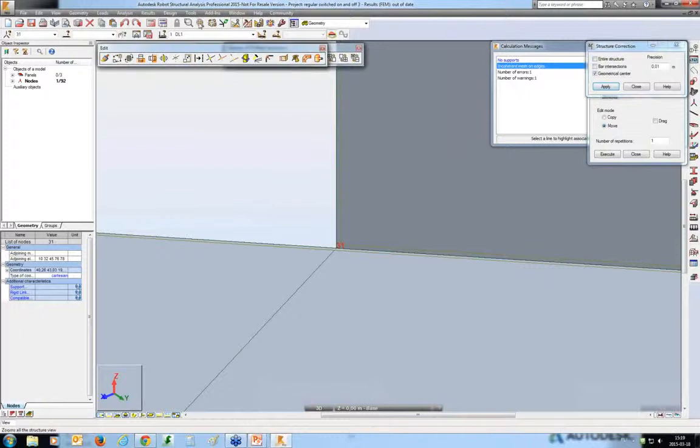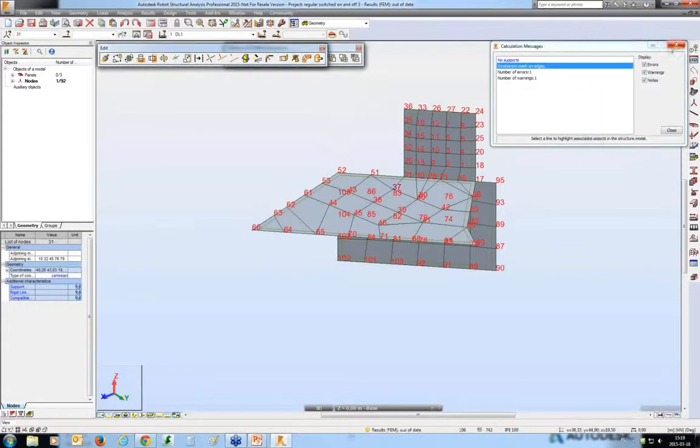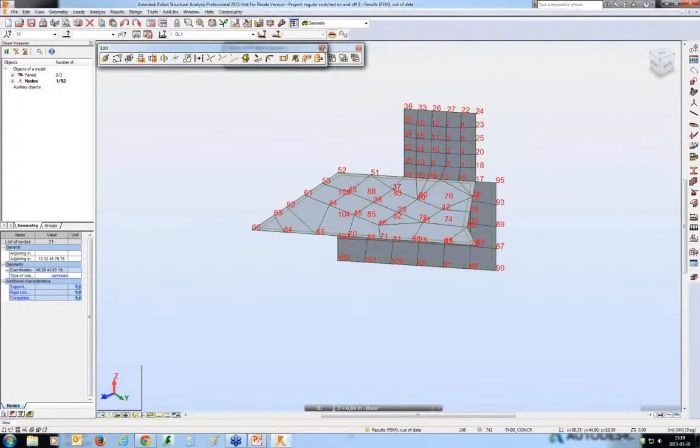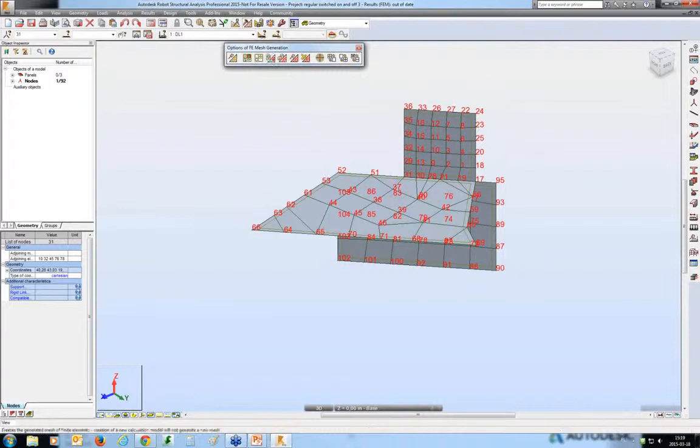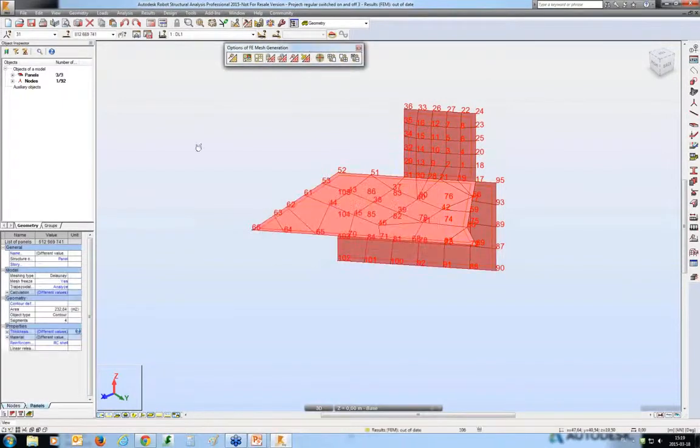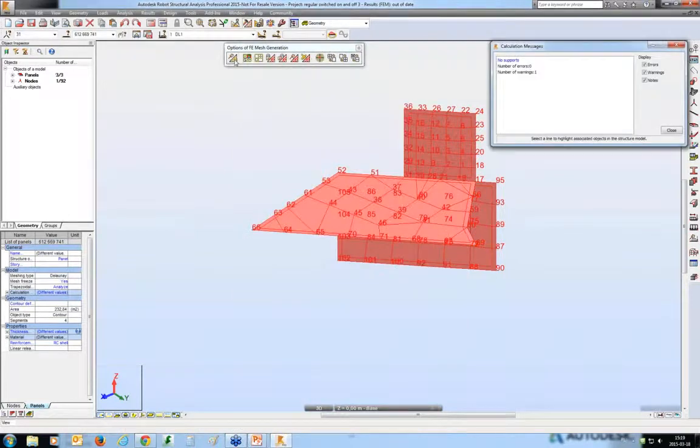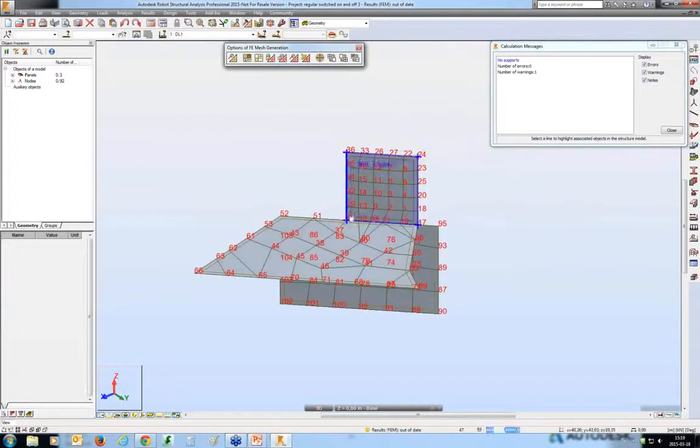What is important is to remember that you should freeze such modified meshes, so when you run model generation again, these meshes are not reset to the original settings. And as you can see, there is no incoherent mesh reported.